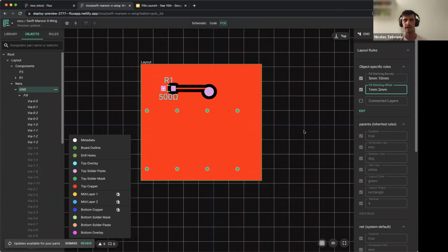Density usually depends on what type of signals you have, like the frequency of those signals. So the faster the signals you have, usually the closer you need each via to each other, so that whatever resonates is higher up in the frequency range.